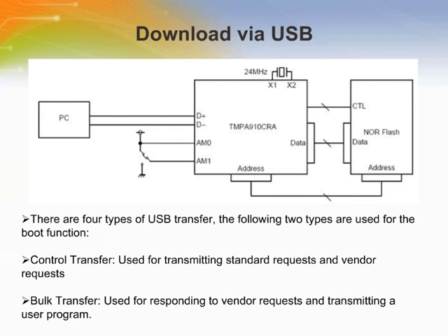Set the oscillation frequency for the X1 and X2 pins to 24 MHz when booting using USB. The USB of this microcontroller supports high-speed communications. However, if the USB host does not support high-speed communications, USB 1.1 or older, full-speed communications will be carried out. The boot ROM function does not support clock supply from the USB clock pin X1USB.